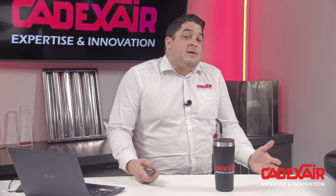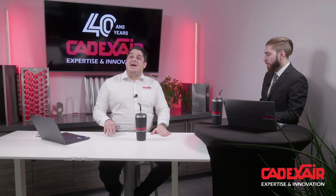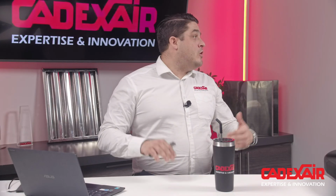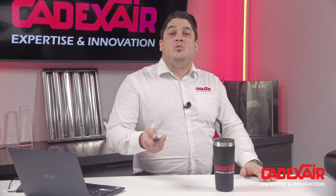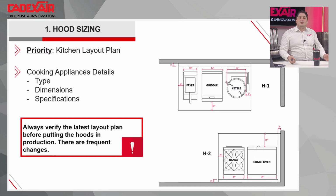I think the last time to double check is every time you put a drawing in production. Always double check that the version used to do the hood drawing and the final actual drawing are matching, to be sure the hood is right. Sometimes there's a small thing that could look like not a big thing, but if you take this example, we have a griddle in H1 and a 4-burner in H2, both 24-inch. They have almost the same airflow, so if you switch them, it looks really simple, but on the other hand, the fire protection system could change or have modification.